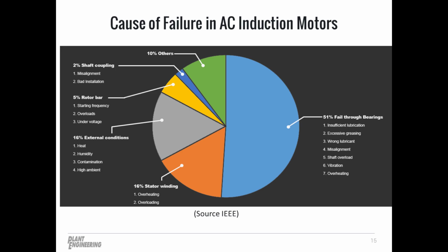You also may notice that overheating and overloading are common to many of the failure types listed. It's very important for the motor not to be overheating. That definitely leads to premature failure. And it's also important to understand the application to avoid the overloading issue. Overloading for increased periods of time will definitely lead to overheating of the motor itself.